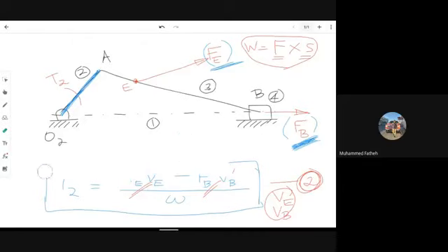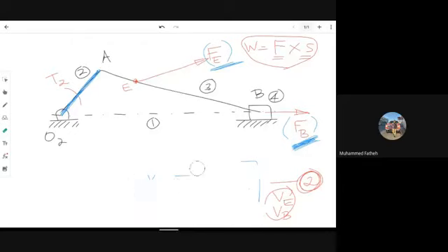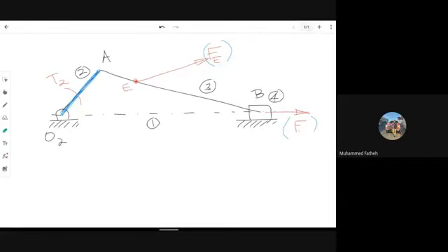So now initially I told you you have to draw the configuration diagram first. After drawing the configuration diagram, you can take the corresponding scale and draw the configuration diagram and all. Then after that we can apply the principle of virtual work to this corresponding situation. How do we apply that? For applying the principle of virtual work, see in the equation, we are directly related to the velocities. So from the initial first module itself, we know the method of finding velocities with respect to any given mechanism. That means we have to draw the velocity diagram.